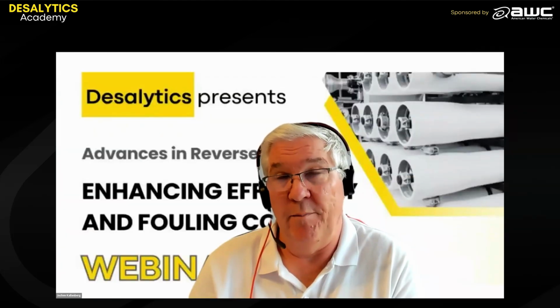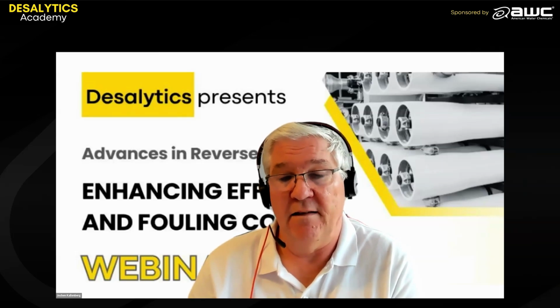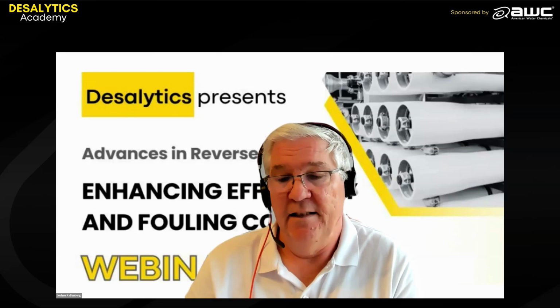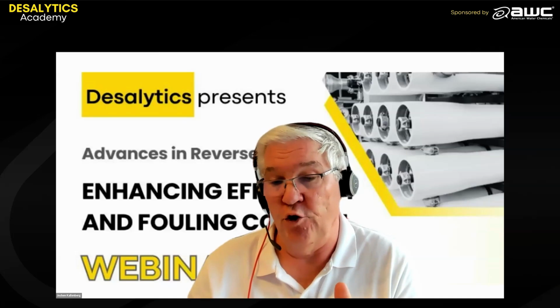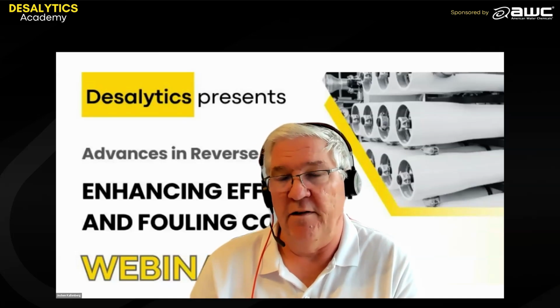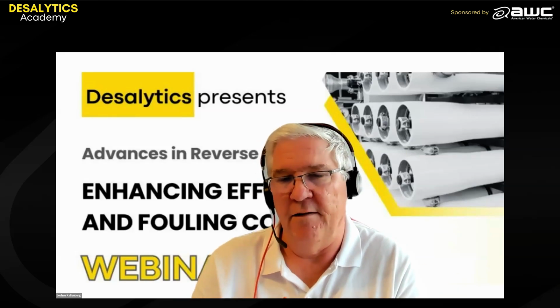Last question I'm going to take is on the benefits of using AFM for groundwater. In Africa, we have a lot of challenges with groundwater. Does it help to increase the recovery or reduce the turbidity further with groundwater? Yes. One of our most used applications in Africa is borehole water, very often containing iron and manganese, sometimes even fulvic acids. These can be precipitated before infiltration. We have good performance in reducing the turbidity to very low levels. It is quite a frequent application in Africa, these typical borehole applications with maybe humic, fulvic and iron manganese content.